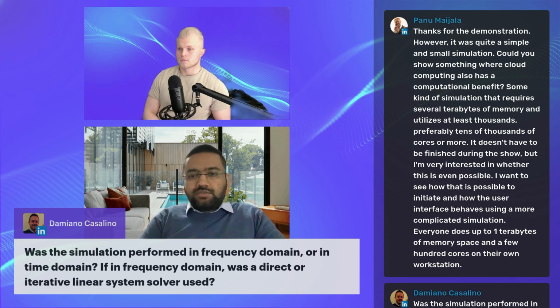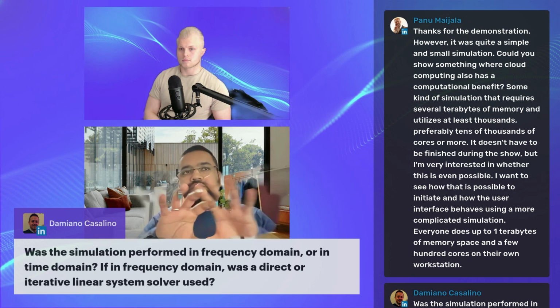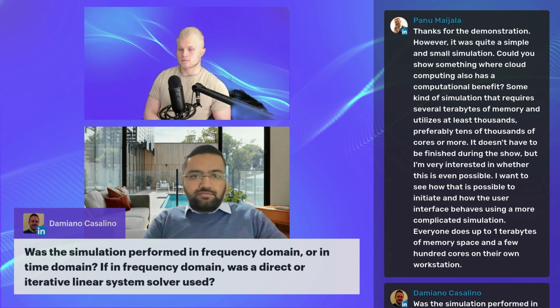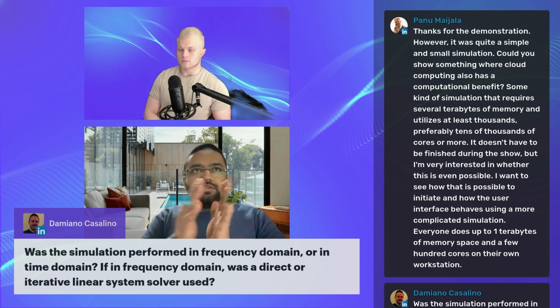And just to avoid confusion about the iterations that you saw, the GMRES iterations, those were for the domain decomposition method. When we divide the domain into several pieces, each of these pieces is solved on a separate core as a separate, let's say, finite element model itself, and it takes the boundary or the interfaces as the boundary conditions.